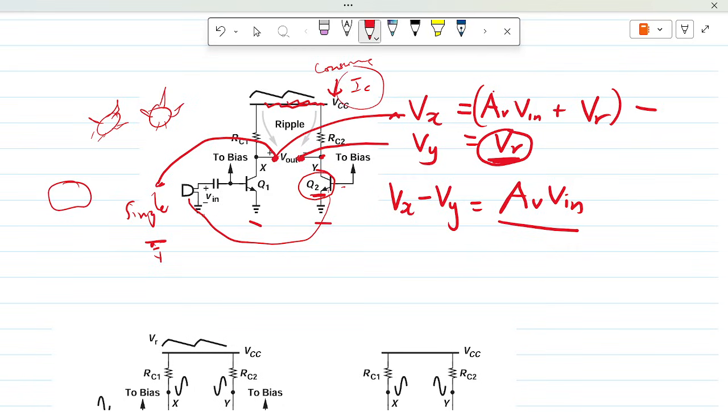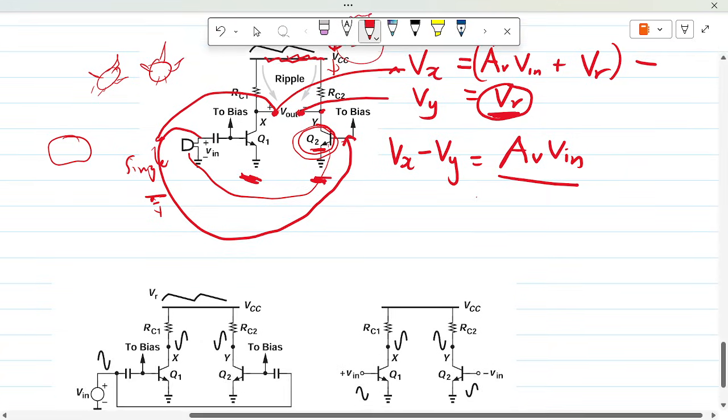What if we could add the signal also to Q2 and get somehow double amplification? So we get some amplification from Q1 and some from Q2 as well, together with noise cancellation. It would certainly be better than having Q2 staying biased and just consuming power. That is only if it's going to work out well.